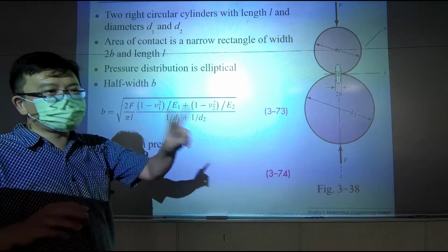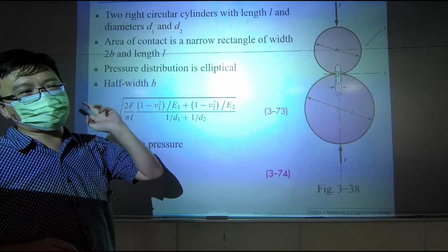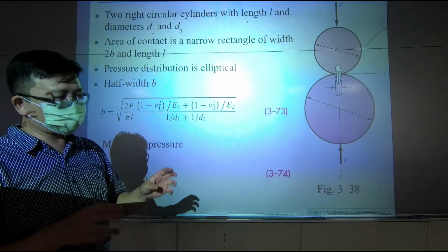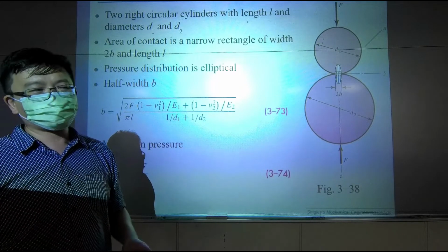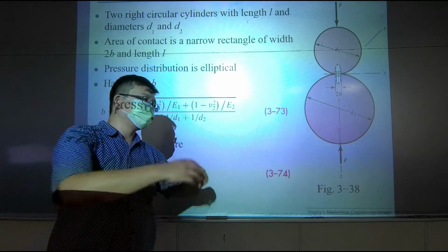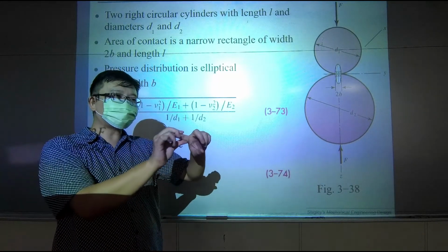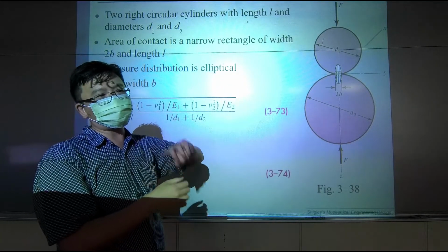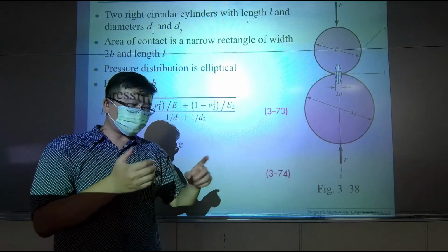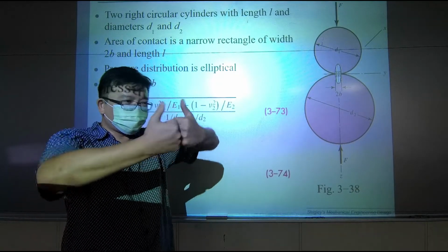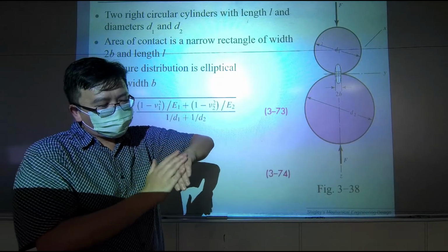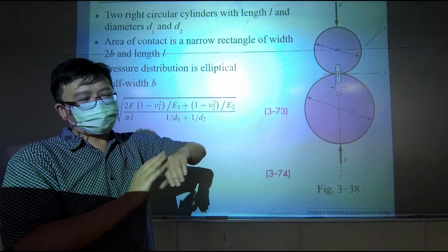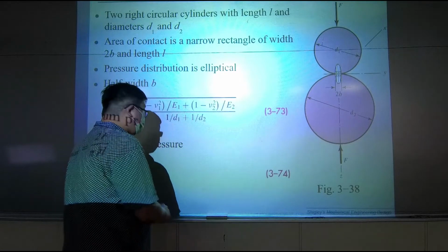So there are two kinds of damage to the teeth that will lead to failure. One kind is when the teeth bend too much and break. That is based on bending stress. The other kind is when the contact stress is too high and the profile is damaged. You have wear. Do you know wear?